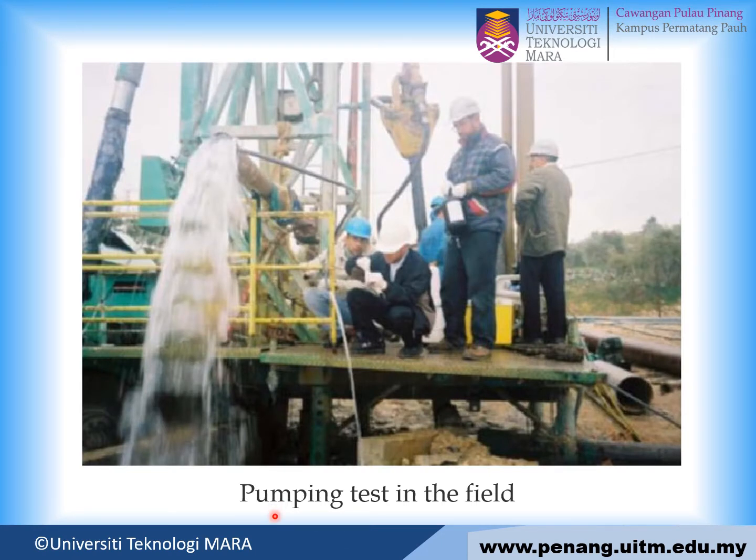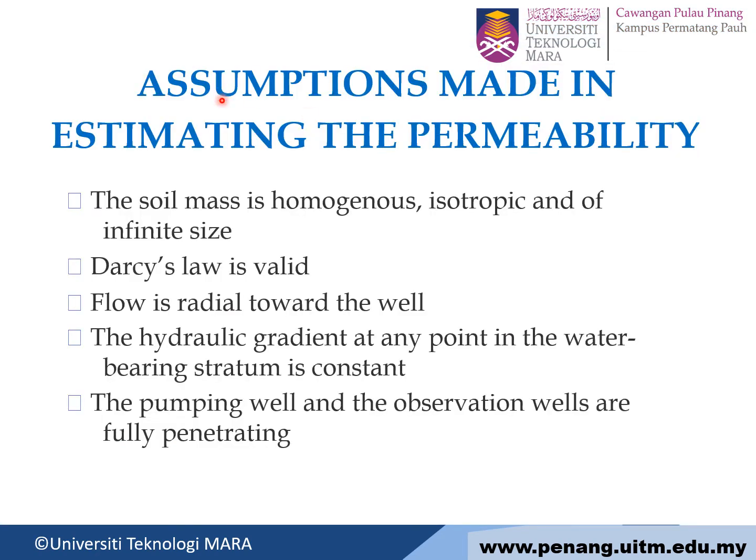This is an example of pumping tests in the field. For the pumping test, we are pumping out the water. Assumptions made in estimating the permeability. First, the soil mass is homogeneous, isotropic, and infinite in size. Second, Darcy's law is valid. Number 3, flow is radial toward the well. Number 4, the hydraulic gradient at any point in the water-bearing stratum is constant. Number 5, the pumping well and observation wells are fully penetrating in the soil.